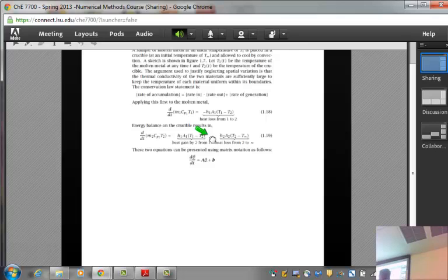So this ordinary differential equation can be put in a vector matrix form, where theta is your unknown vector consisting of T1 and T2, and A is your, now is this problem linear or non-linear? T1 and T2 are the unknowns, and they appear by themselves. All the products of that are constants, they are known. Okay, so that is a linear model, and if it is a linear model, you can write it as d theta/dt equal to A times theta plus B. A is a matrix of numbers, and B is a vector of numbers. It will be a 2x2 system, two equations and two unknowns. T1 and T2 are the two unknown functions that we want to find.